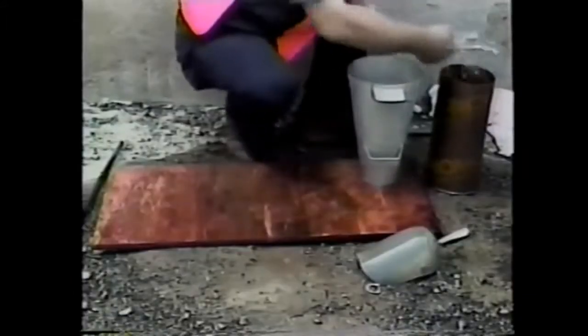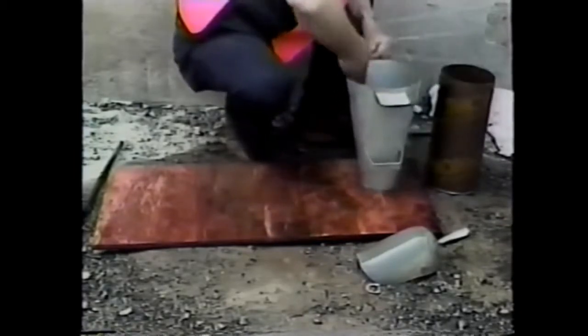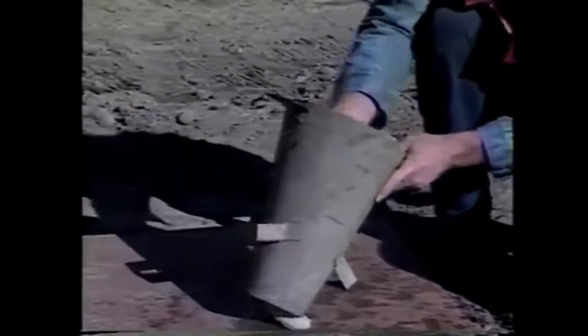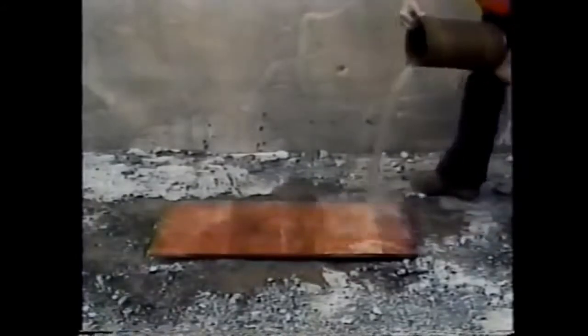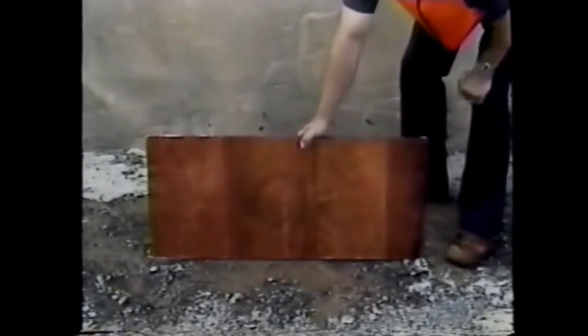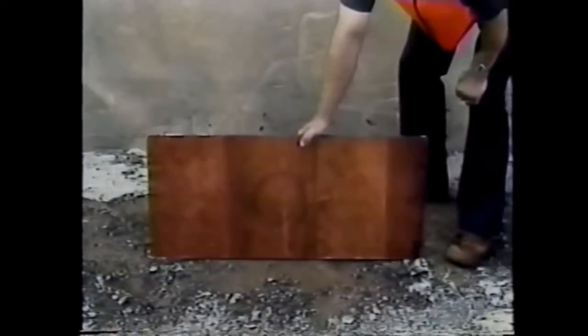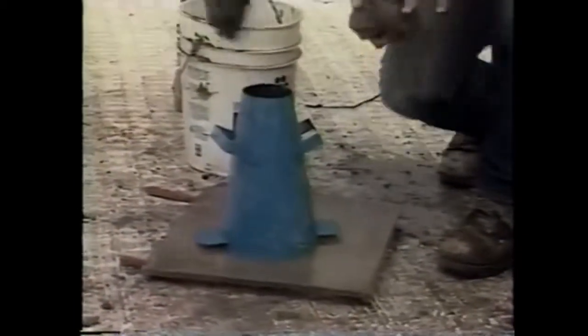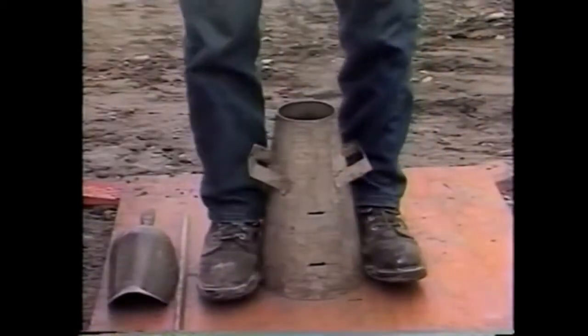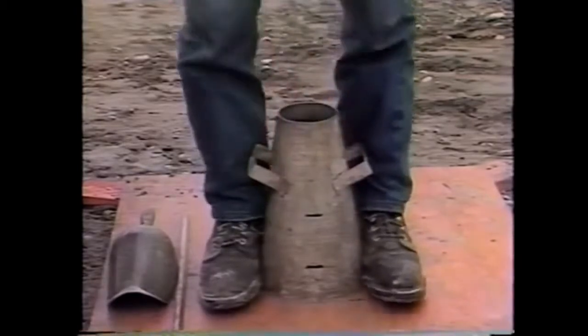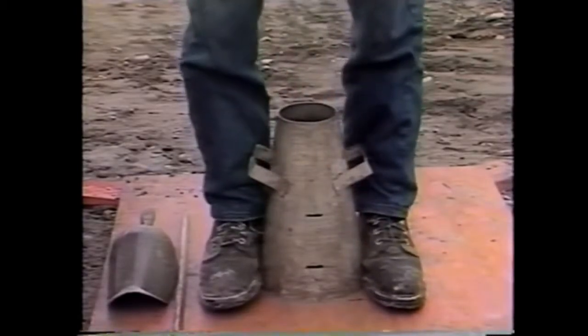The test is begun by first dampening the inside of the slump cone to keep the concrete from sticking to it. Then the base is dampened as well, so that it won't absorb water from the concrete. But no freestanding water should be left on the base. The cone should be set down on the base as close as possible to the sample. Next, the technician steps onto the footholds at the bottom of the cone and stays there. That's why the sample and cone need to be close to each other.